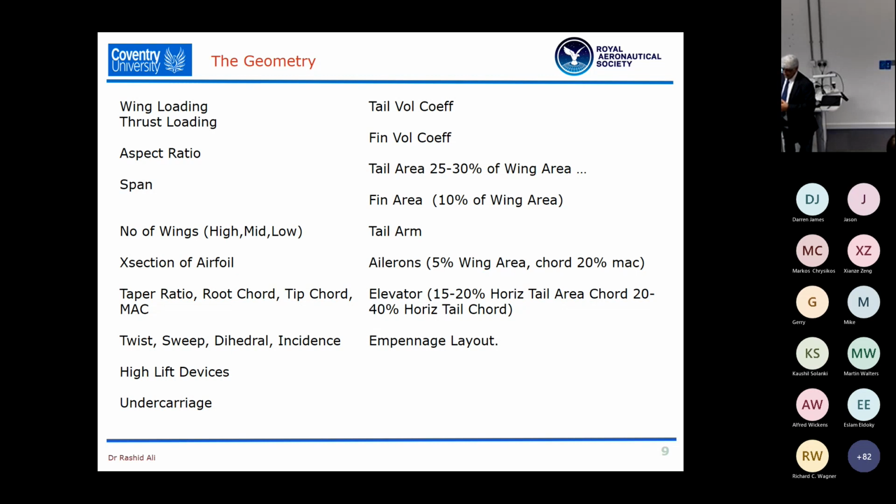Now, from a simulation point of view, those empirical numbers are good enough. But then, as you will see, if the aircraft lacks the performance, using a software tool such as X-Plane will allow you to very easily, quickly change some of those areas and rerun the simulation, seeing the effect of that parametric change.